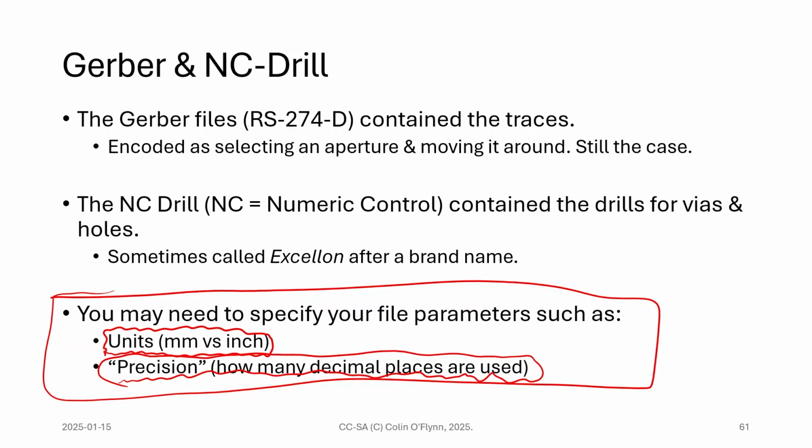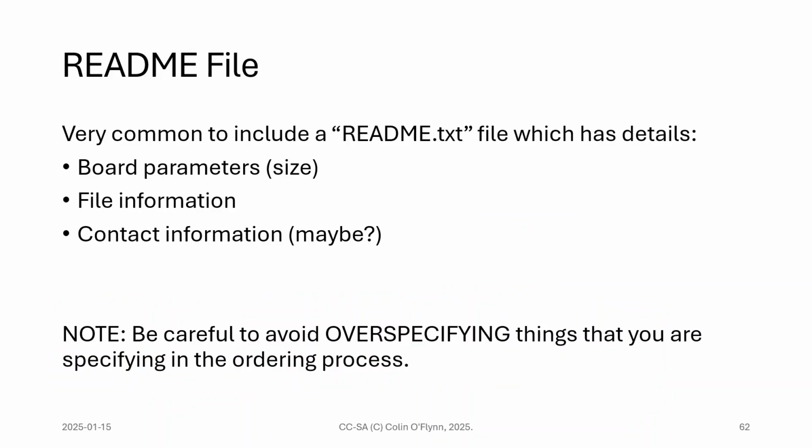Most of the time you can just accept the defaults, but if you run into issues, you may have to go dig into that. The other thing that's common to include is a README file. This is just a simple text file that has the board parameters, like the size of the board, which is nice to show, what files you've included, and maybe your contact information if they have questions.